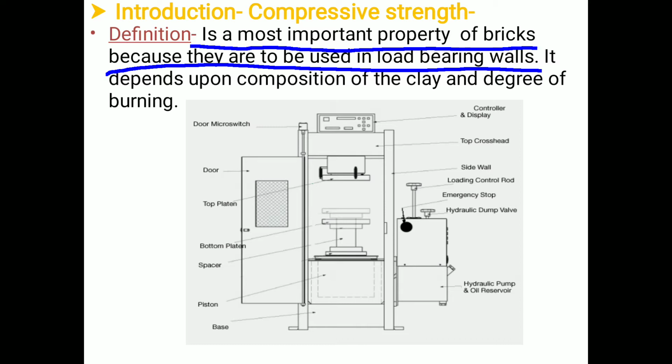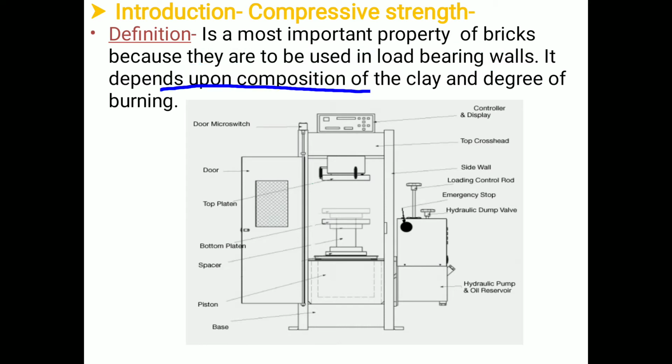So in today's practical, we are going to determine the compressive strength of the brick. Remember that the compressive strength of the brick depends upon the composition of the clay and the degree to which it burns.